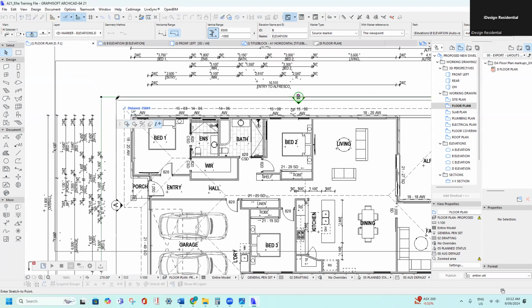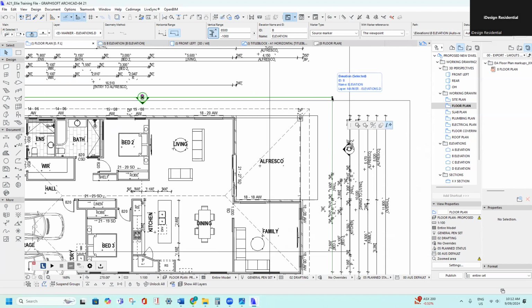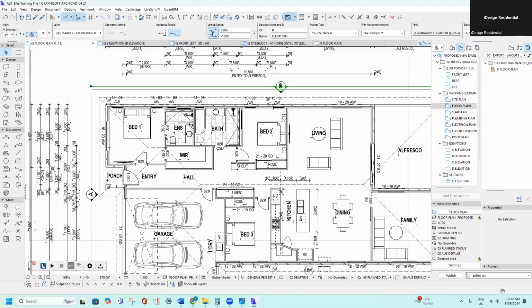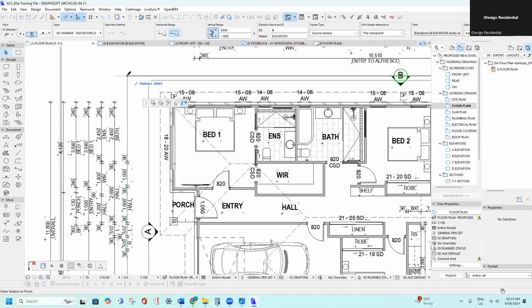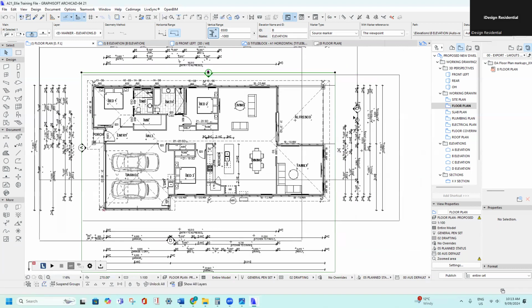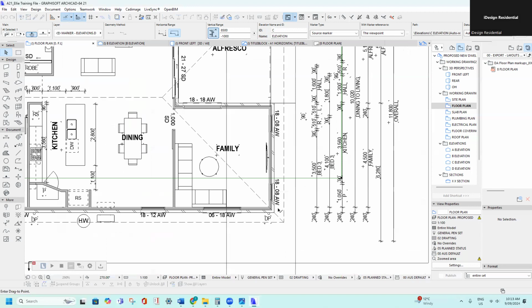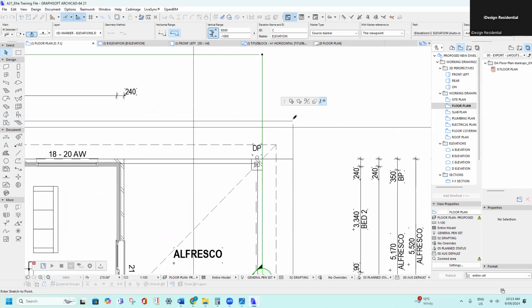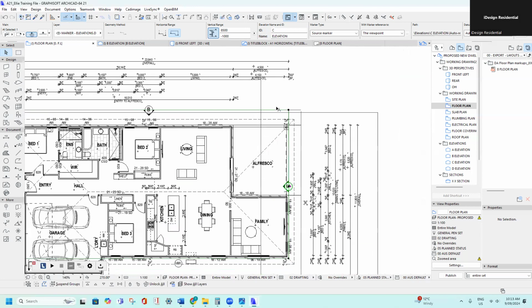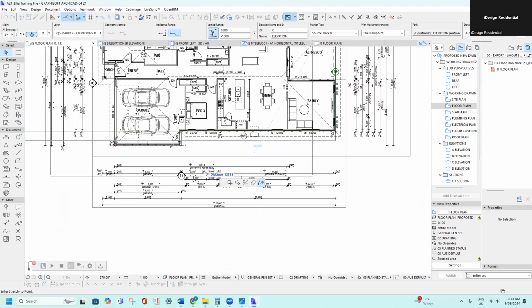We can actually make them overhang 1 meter. So if you line it back up with that, that'll be a 1 meter overhang. Actually, yeah, so just make them 1 meter overhang, sorry, not 2 meters. And then if you click on this elevation marker, you can basically line it up with the one that's already been put in there, because they're all 1 meter off anyway. So if you drag that down to that one,